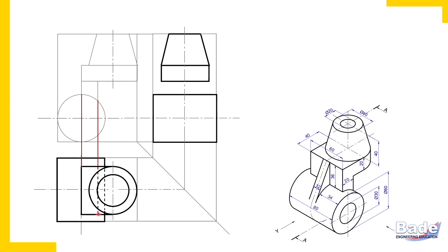Okay. Now let's draw this plate in the side view. Watch here, this is that plate. Focus on the plate and draw projectors from the top of that plate and from the lowest point on that plate. That is height. From the lowest point to the highest point, that is the height of this plate. So this is how we have transferred it from front view to side view. And now the width of this plate is 60 millimeters. So project it in the side view. Okay, this is 60 millimeter, which we have already projected earlier for this upper U-shaped plate. So this is the rectangle.